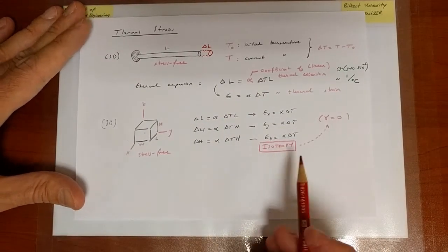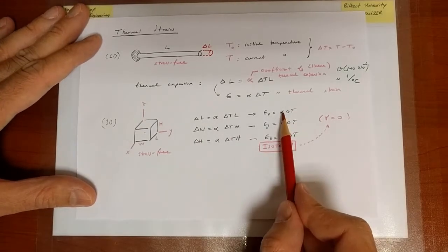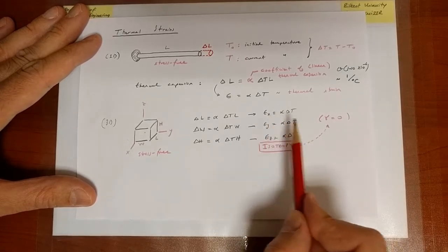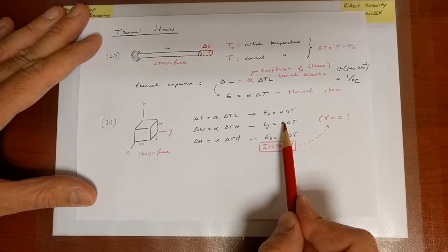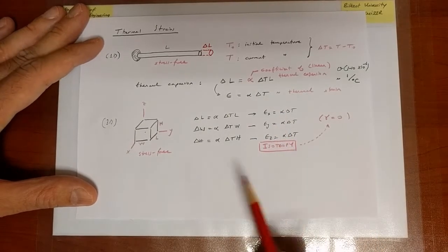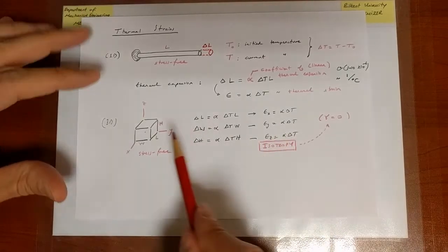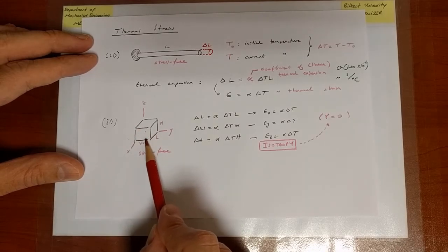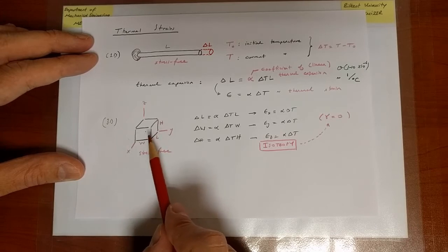So it turns out, therefore, you might suspect that if the material is an anisotropic one, you will in general have different amounts of strains along every direction for a given temperature change. So these will be different factors, alpha x, alpha y, alpha z, for instance. And moreover, what you will observe is that the shape of the angles, which are initially pi over 2 in this simple example, might increase or decrease depending on the coefficients that govern it.